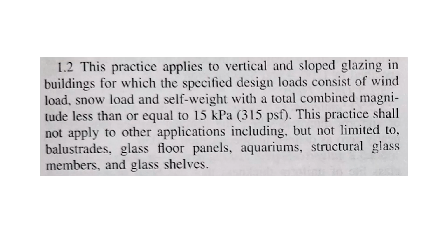Okay, this practice applies to vertical and sloped glazing, all right, in buildings for which the specified design loads consist of wind load, snow load, self-weight, okay, the weight of the glass itself, with a total combined magnitude less than or equal to 15 kilopascals, or 315 pounds per square foot.